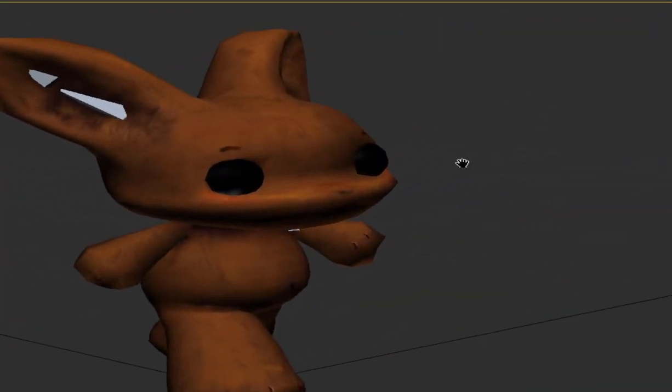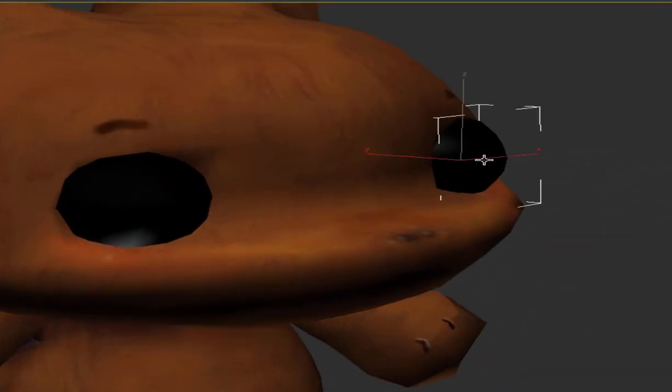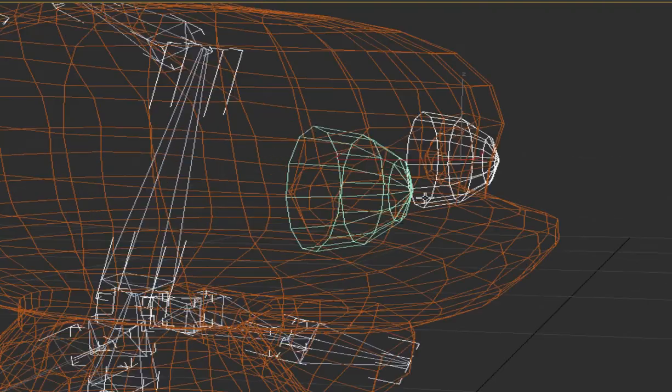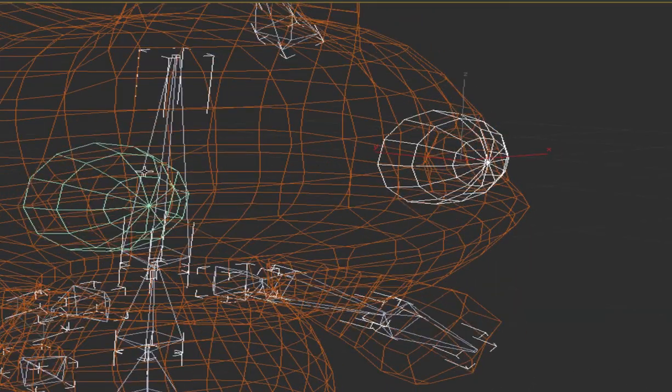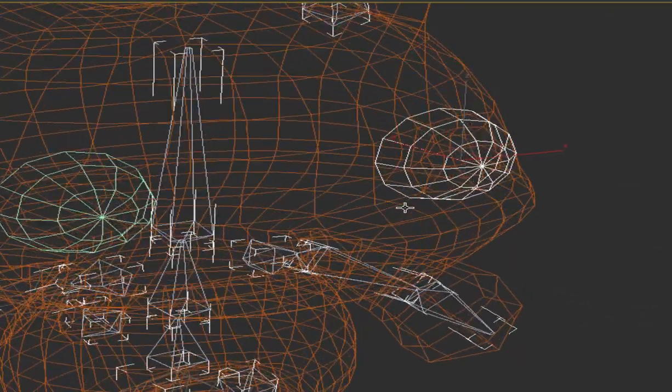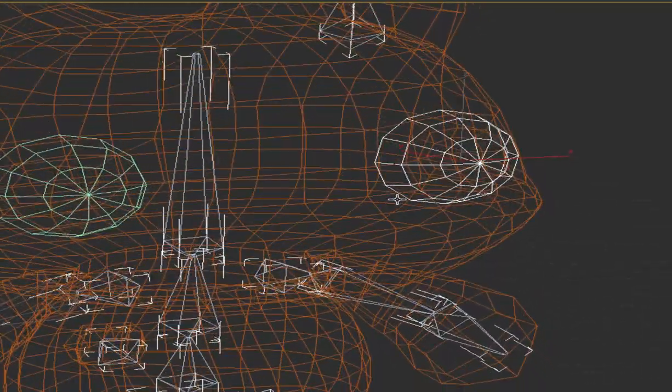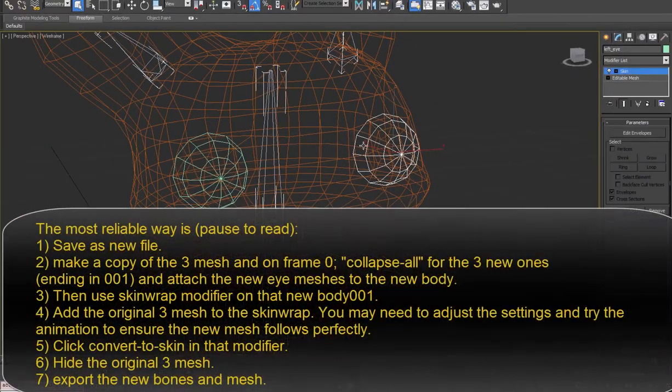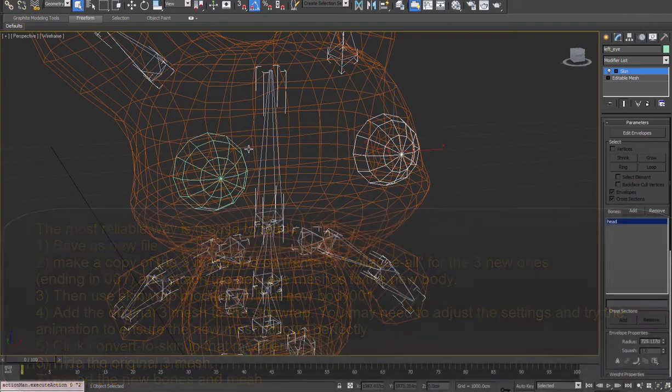I would note that if you have extra objects in your scene and you're parenting the object directly to a bone, I don't think it's going to work right. Not in this style of the skin mesh, it doesn't import correctly. So what I would do in that case, if you wanted to keep that extra model piece, is make a bone that comes down from here, and then one that goes out to this eye and one that goes out to this eye.